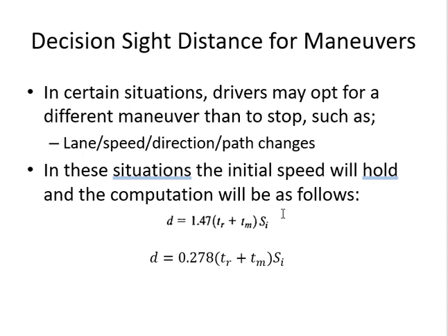Now I showed you the ramps, right? Ramp going in, coming out. Should the driver stop there? No, right? Stopping can create a crash, so stopping is unsafe. If the location is like this, I know it's a complex location, and I know the driver will not stop, so providing stopping sight distance doesn't make sense, since I don't want the driver to stop. In that case, we have another equation to calculate the distance for other actions. For the time being, to make our life easy, all other actions use the same equation.